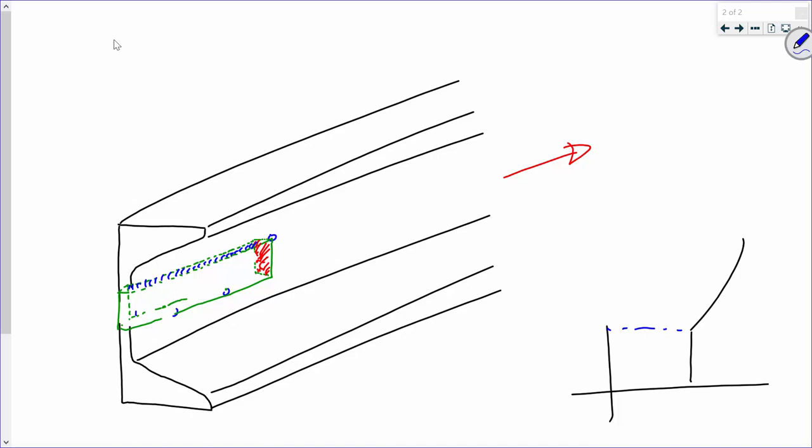Does that make sense? But that is only half of it, right? The full gross area in shear, if I trace all that out, is actually down here. See what I mean? So for gross area in tension, it's going to be this length times the thickness. For gross area in shear, that length times the thickness times 2. Does that make sense?